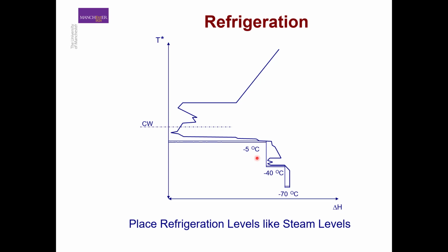So this is the optimal use of refrigeration to supply our process with the cooling that it requires, and doing it at the cheapest possible cost. However, we have to take into account that supplying these three levels of refrigeration for our system is going to be much more complex than just supplying the -70 degree centigrade utility.